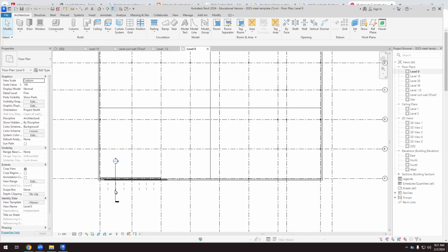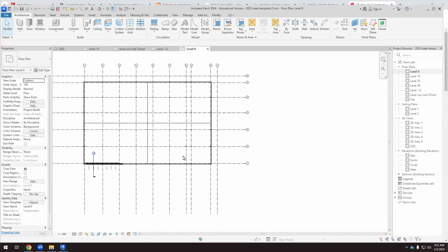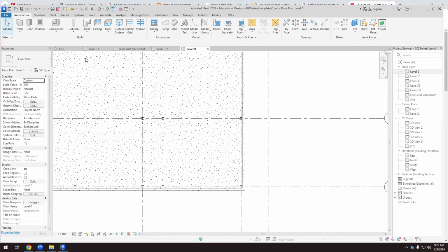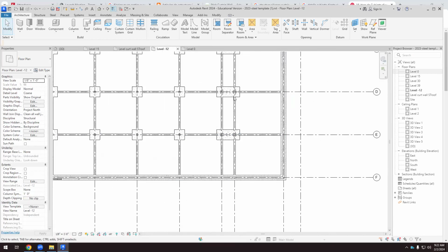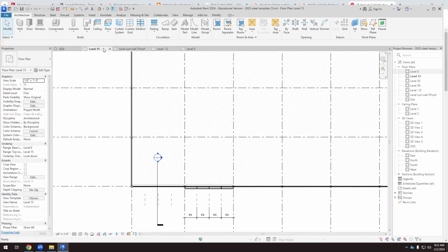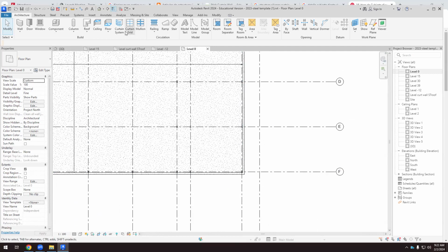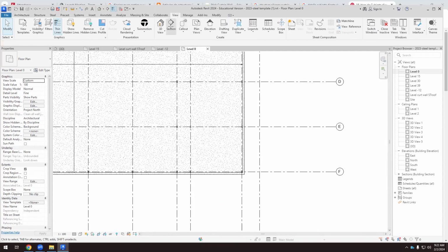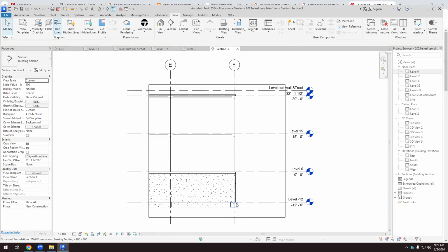Now we're going to design a staircase. We have all the stuff that we have done here for the opaque wall and the curtain wall, and we're going to design a staircase that goes from level -12, this level, to level 15. That's the goal. So first, I'm going to create a section here: architecture, no, view, section. I want a section here because I want to see what I have.